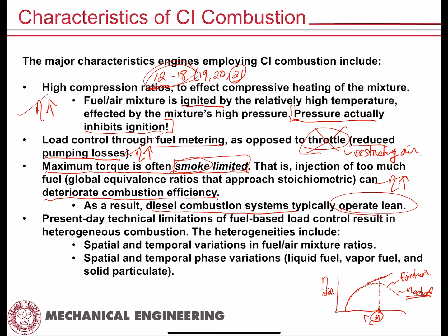But secondly, you also learned this semester that efficiency doesn't depend on the amount of energy you give something, right? The more energy you give it, the more work you expect out of it. So there's something more inherent to the design of a diesel engine than just the type of fuel it uses. And it's these reasons, okay? Now, of course, it is true that the fact that we're using compression ignition combustion gives us these features, right? Compression ignition gives us the need for a high compression ratio, right?